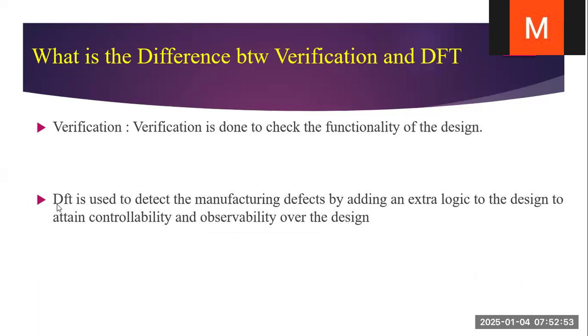In case of DFT, it is easy to detect manufacturing defects by adding extra logic to the design to attain controllability over the design. So it requires fewer test patterns. Extra logic is added, less time. DFT will check the correctness of the design, and verification will check the functionality of the design.